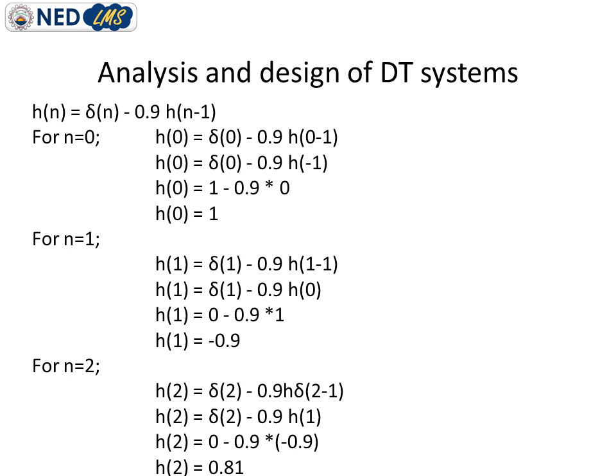Now again varying for n is equal to 2. For n is equal to 2, our equation becomes like this. The first function becomes 0 for other values of n, for n is equal to 2, 3, 4 and onward. But the impulse response term is basically that which we obtained in the previous step, which is minus 0.9. So h at n is equal to 1, which is the answer obtained in the previous step, is minus 0.9. So we place minus 0.9 here, and minus 0.9 is the actual coefficient, so after multiplying we get positive 0.81.